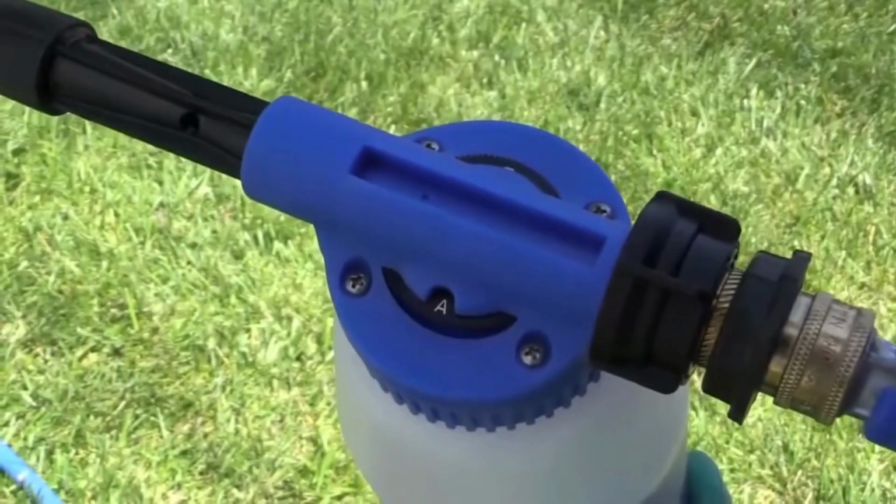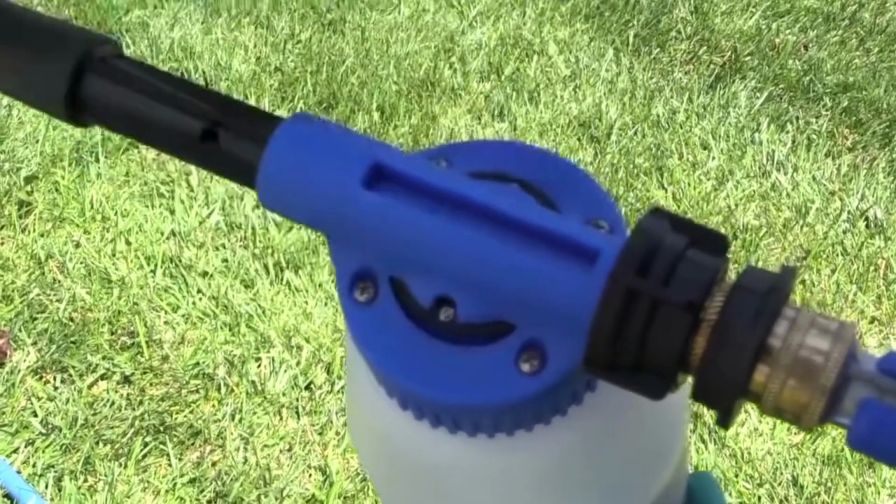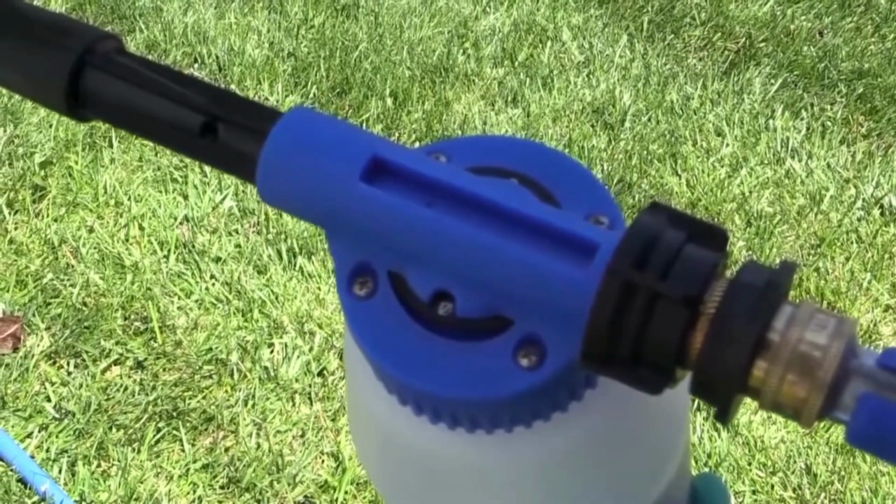Allow the coil cleaner to remain on the coils for 5 to 10 minutes depending on the severity of the debris. Once the dwell time has finished, either switch the coil gun to the rinse position or simply remove the sprayer handle from the coil gun and begin rinsing the surface of the coil.